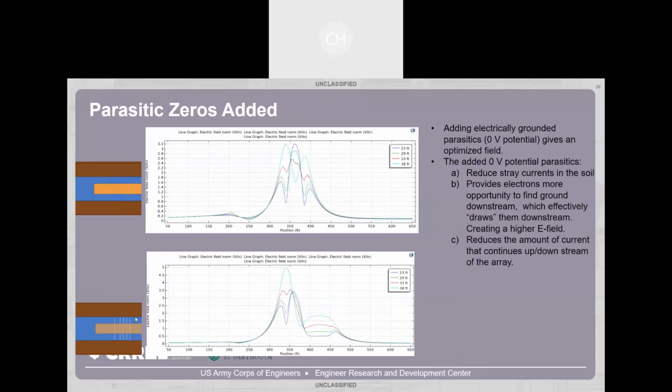One thing we've also looked into and talked about with Brandon Road is that Romeoville put in these giant, they call them parasitics. So they put in these giant sheets of metal kind of to the left and to the right, anode and cathode, because one issue that we're trying to mitigate is stray current. Unfortunately, those parasitics at Romeoville were not electrically connected to anything.